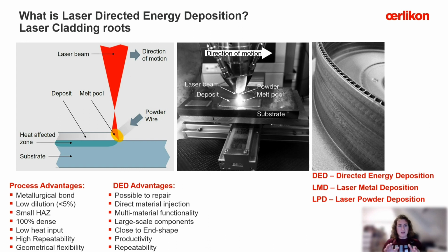And finally, what is important to understand about DED, you have no size limitations except the limitations of your equipment. If you need to build a component 3 by 3 meters in width and length and the same in height, well, if you have a machine large enough for that, you're not limited in terms of technology. And this makes directed energy deposition a very attractive process.